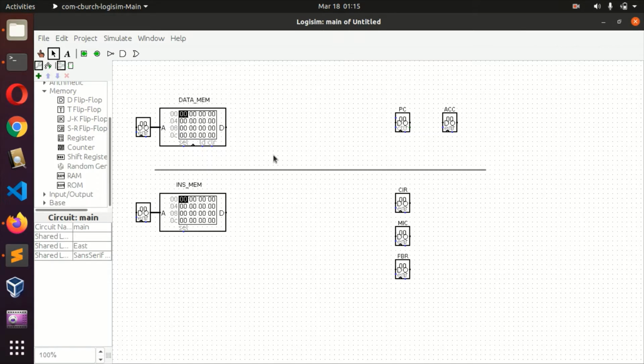Now, there are two ways of implementing this common bus topology. The first approach is using a multiplexer and a demux. Using a combination of these, you are able to create the common bus topology. But there's another approach too, which is the use of tri-state buffers, and that one seems to be much easier to work with. So we will go with that one, the tri-state buffers, and later you'll see how that comes into play.